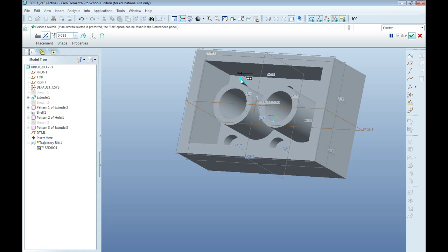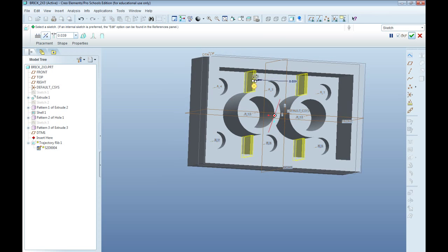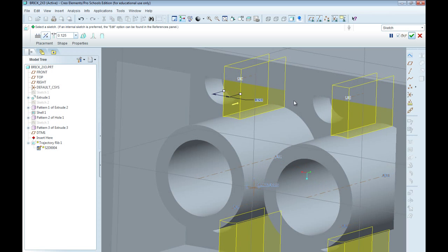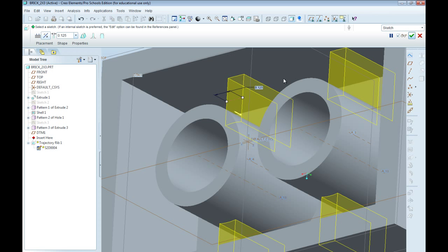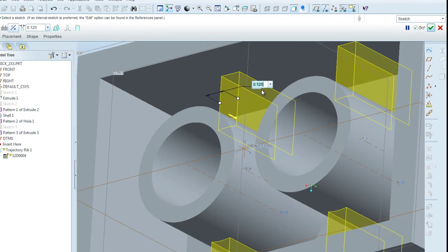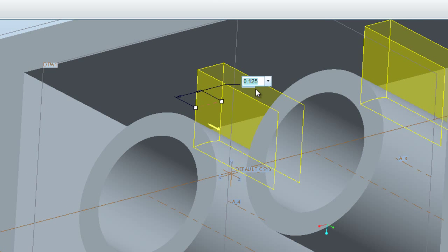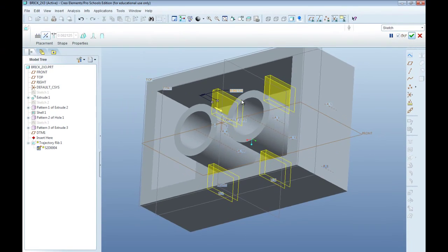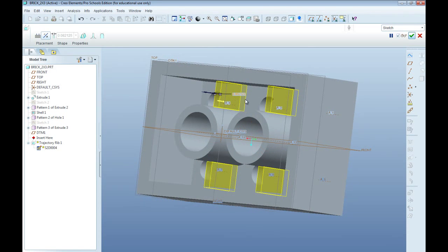We'll set the direction of the extrusion, or our rib. So you'll see now we have our set of ribs created, and we have the set of thickness. We can see that the rib is flush with the outer surface and also the inner surface of the part. So from here, we'll set this as, I think it should be, the wall thickness divided by 2. So that is just a preview of our feature.